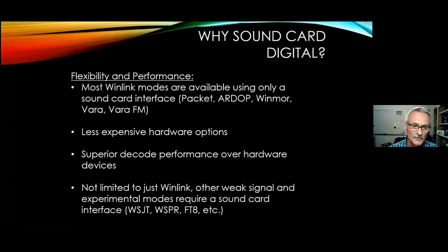They certainly do seem to have a superior decode performance over hardware devices, and I'm talking specifically about packet radio. When we compare a hardware TNC against a Soundcard with a software TNC application, we are pulling packets out of the noise and decoding them where a hardware TNC would ignore the packet altogether.